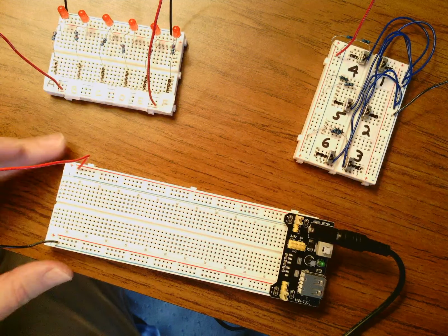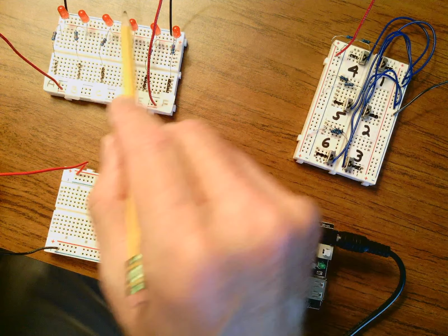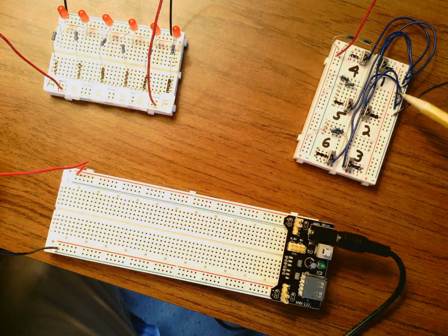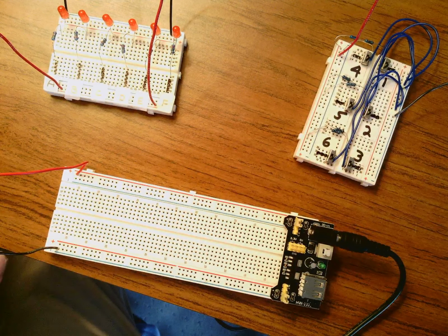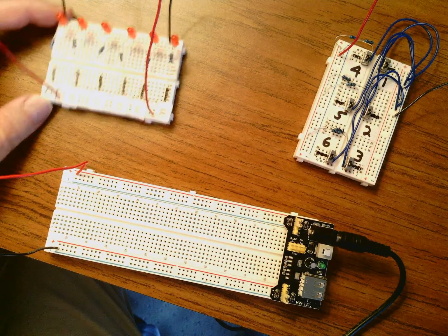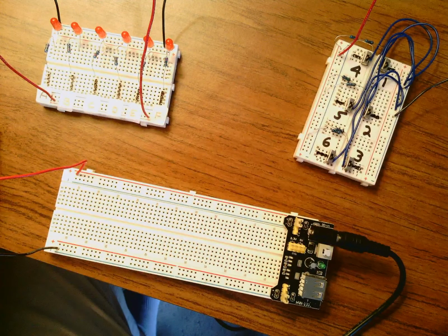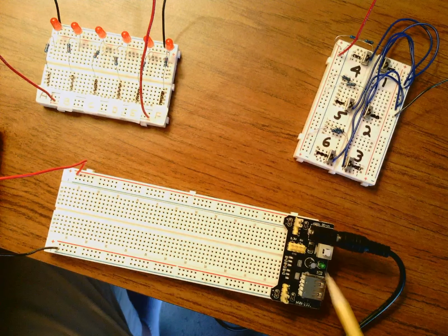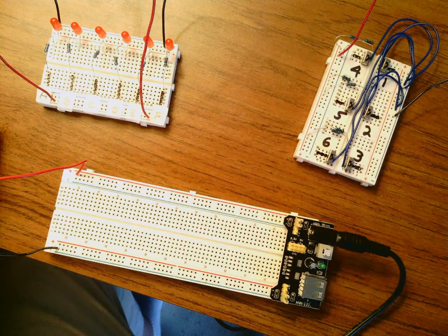But now what I did is I distributed the ground from here to the blue rail and to the blue rail over here. I want you to take a look at that very carefully, because you have to set it up this way every time. You have to get these set up this way every time before you start your lab. And make sure your power supply is turned off when you do it. Then what we're going to do